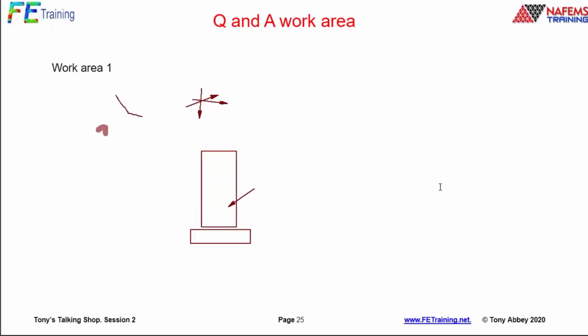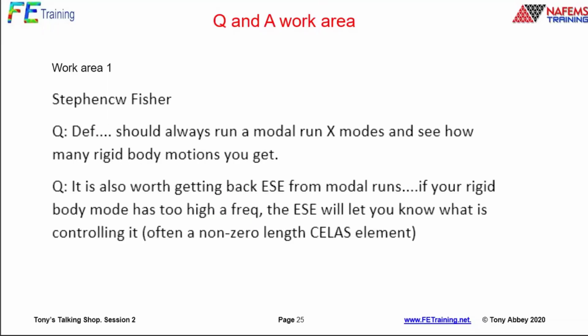Stephen says, definitely should always run modes, modal checkout, see how many rigid body motions you get. Yep, absolutely, Stephen. It's the rigid body modes, but even if you haven't got rigid body modes, are things, this is an engineering term from England, are things wanging around? So that's a genuine engineering term there, which I use a lot on live training.